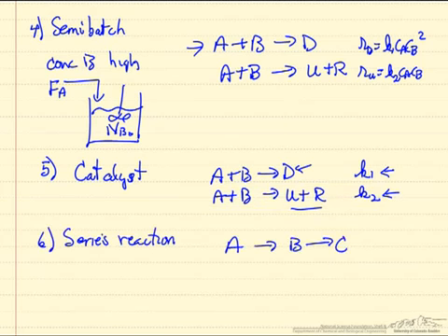The final example we will look at is a series reaction. The previous ones have been parallel reactions. So in a series reaction where this is our desired product, something like partial oxidation, for example, the space-time, the reaction time, affects selectivity, and that can be the most important variable, the space-time. The other way of looking at this is how much conversion do we have?